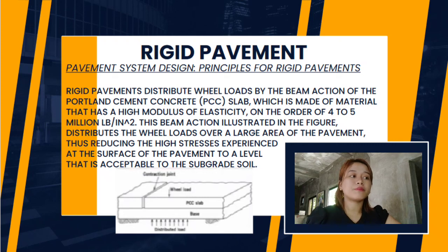The purpose of the pavement is to transmit the loads to our subgrade at a larger area, therefore a smaller amount of stress. So the essential difference between flexible and rigid pavement is the manner in which they distribute the load over the subgrade. For rigid pavement, because of concrete's rigidity and stiffness, it tends to distribute the load over a relatively wide area of subgrade.